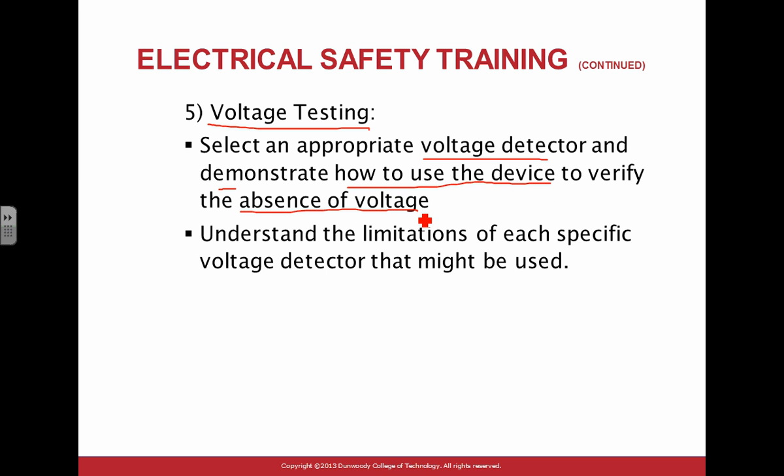You cannot believe, guys, we're recording now, I can't say things that I shouldn't, but people have burned their hands using the wrong meter on the high voltage side, because these meters can literally explode in your hands, through no fault of your own. They're not rated to handle the short circuit or the transient that piece of equipment can create. So you could use it properly and still end up burning your hands or your face, because it is not rated to handle the transient, which you have a lot of because you're mechanical.